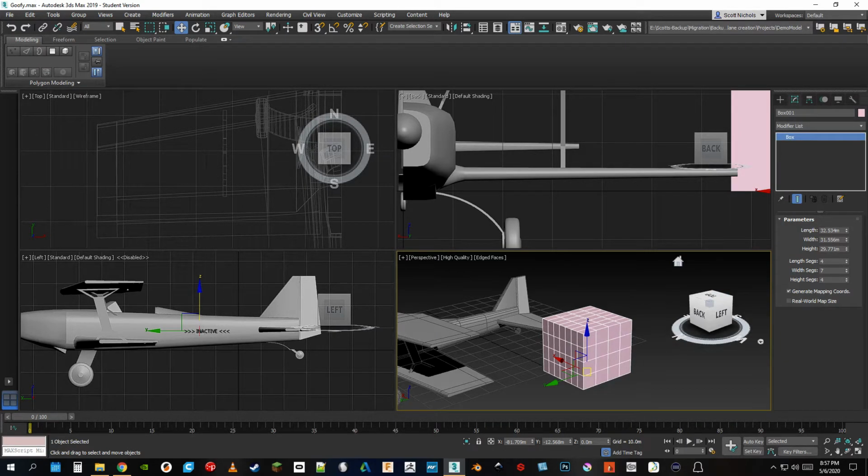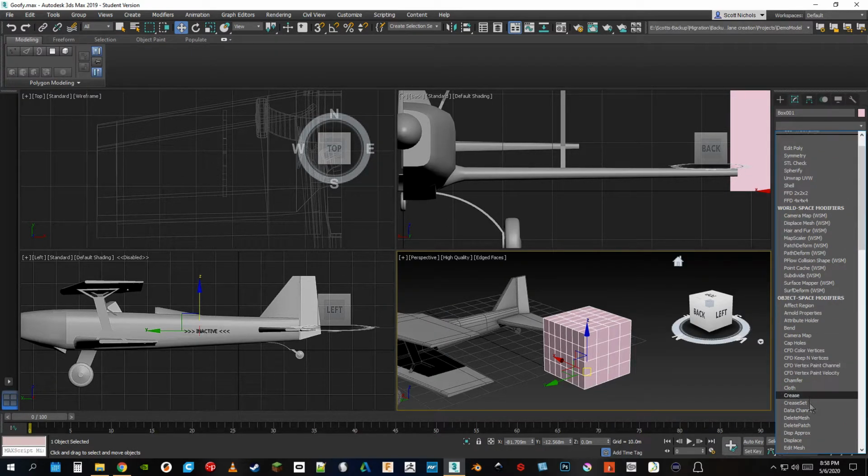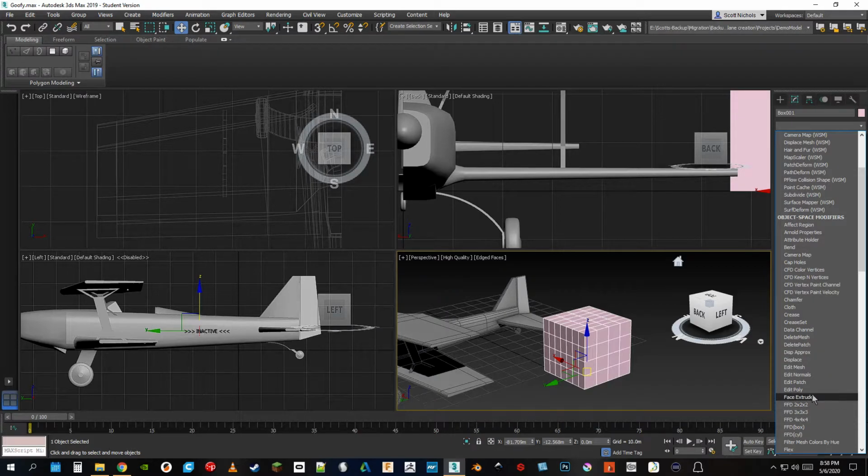And over here in the edit tab, we're still faced with all the same controls, which can be confusing, but it's really just so we still have more control over the object. And from here we could convert this to an edit poly, and we will find that here.